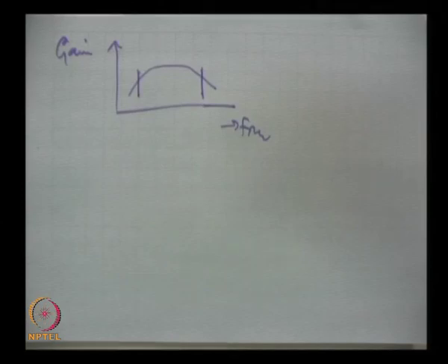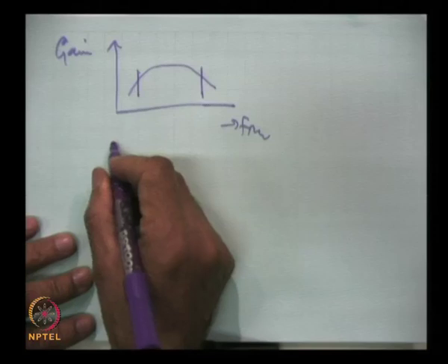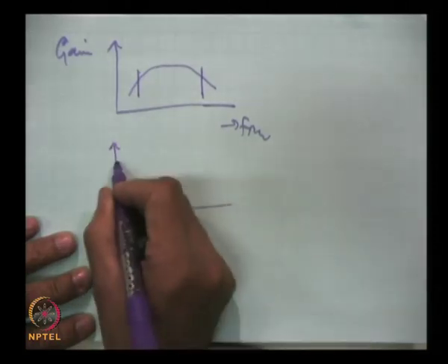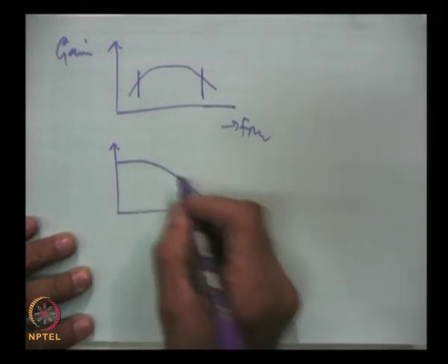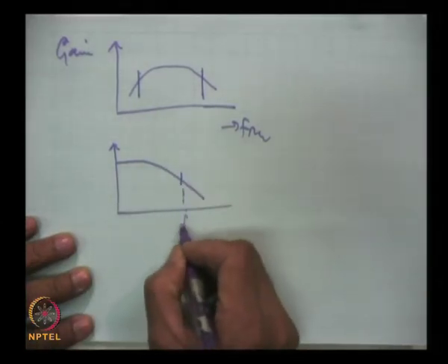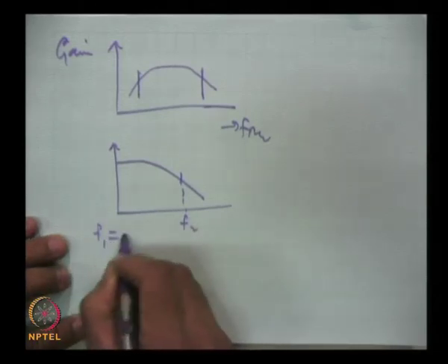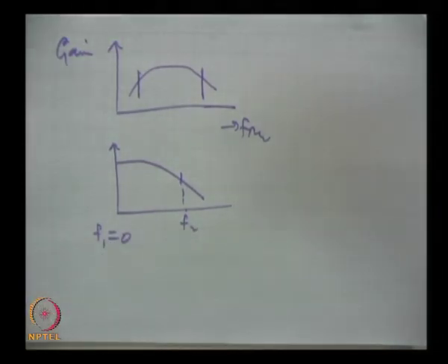In direct coupling there is no limit on this lower cutoff, and hence the frequency response of that direct coupled amplifier is like this, where the upper cutoff of course will be here, but lower cutoff is 0, this is gain. And now, so this is the direct coupling, and the special case of direct coupling we talked Darlington pair, which is the direct coupled two stage transistor and which is sold as a unit.